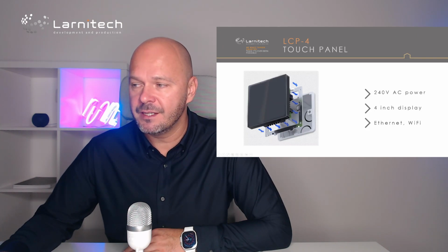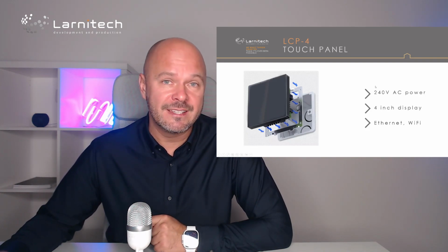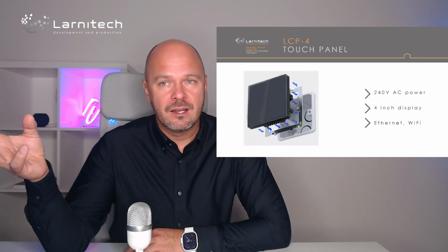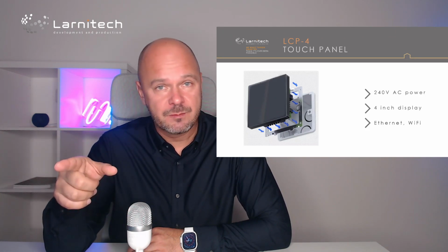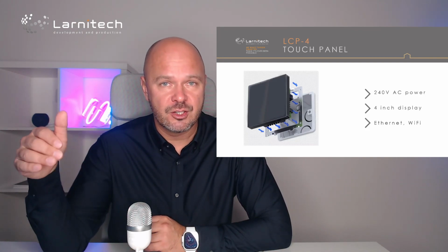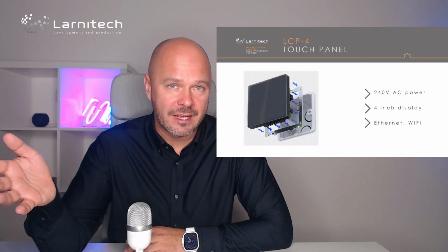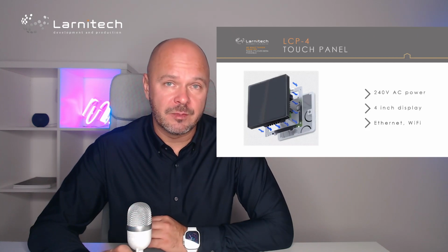So, a 4-inch display, Ethernet. It also has Wi-Fi. Because it has 240 volts AC, you can use it for retrofit. So sometimes behind the standard switch you have the live and the neutral together. So you connect to this panel and then you use Wi-Fi to control all other systems. So you don't need additional wires. This is not the best way, of course. The best way would be Ethernet, the wired control connection. But Wi-Fi is also available.